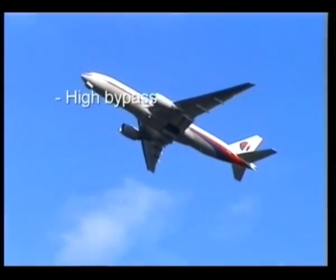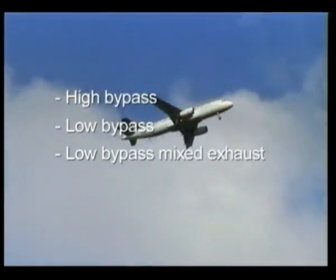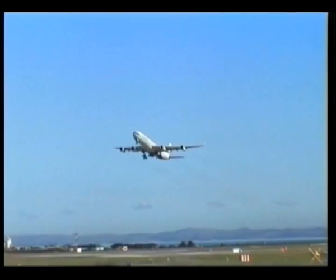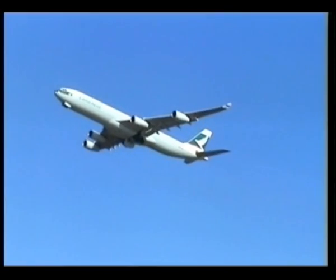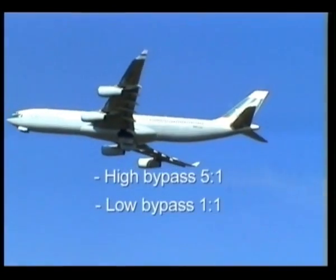They can be high bypass, low bypass with mixed exhaust, or rear fan, where the fan is an extension of the turbine. The bypass ratio is the ratio of air flowing through the fan compared with the air flowing through the core engine. High bypass is about 5:1, and low bypass is 1:1.